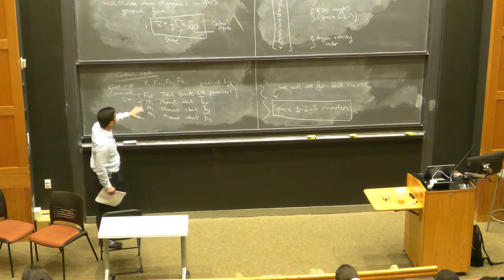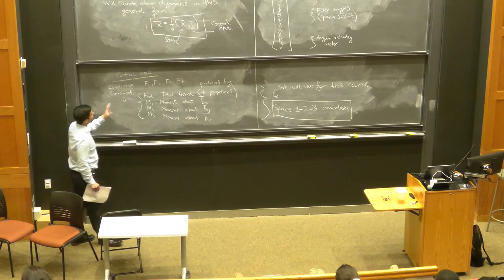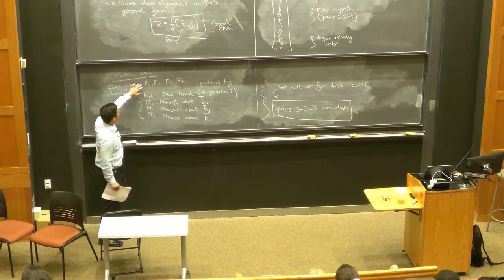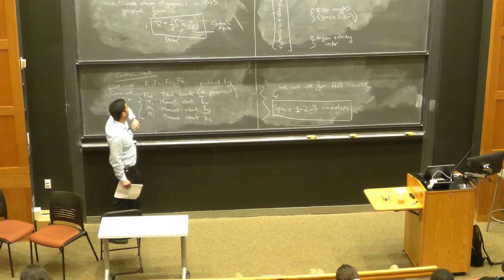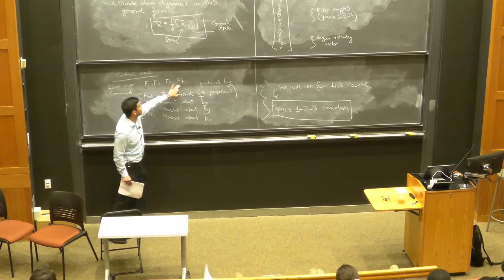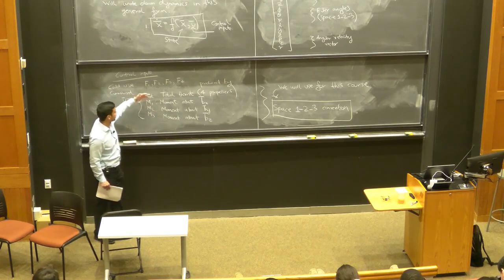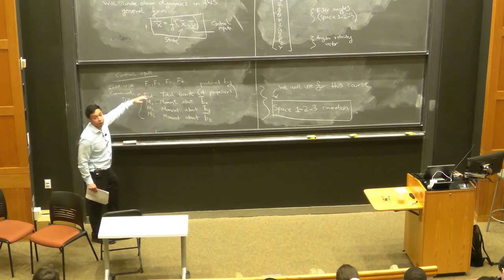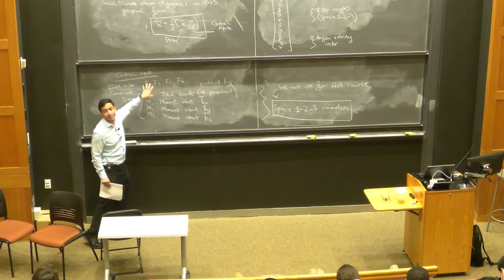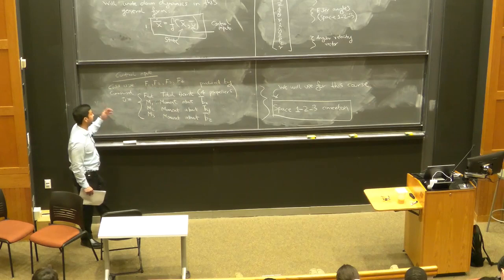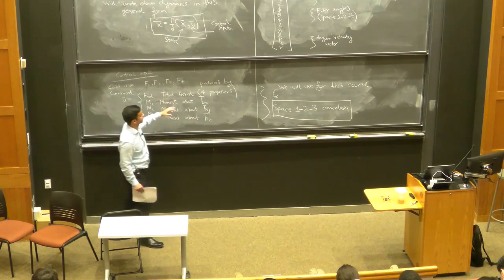I'll go into more detail about this in the next lecture. But as a quick point, you can go back and forth between these two representations. If I give you F1, F2, F3, F4, you can calculate the net thrust and the net moments. And if I give you these four numbers, you can invert that relationship and get these. So in some sense, they're equivalent. But like I said, it's slightly more convenient. The equations look a bit more compact if we go with this representation.